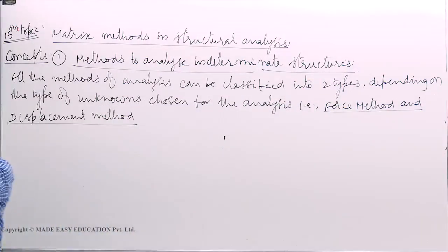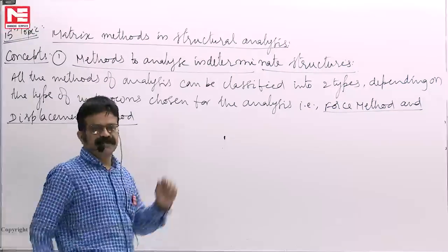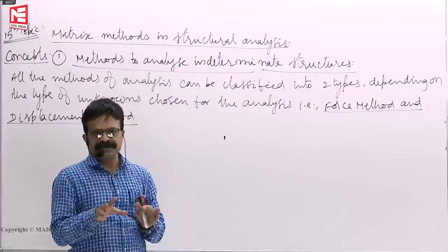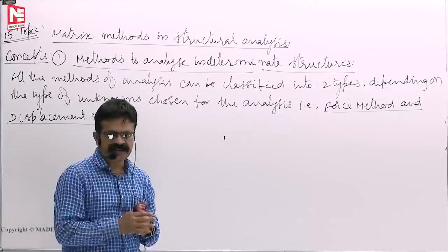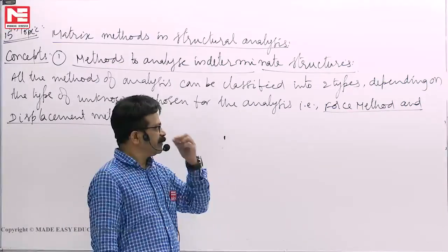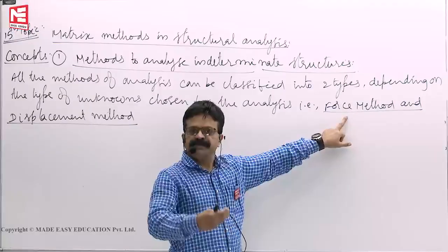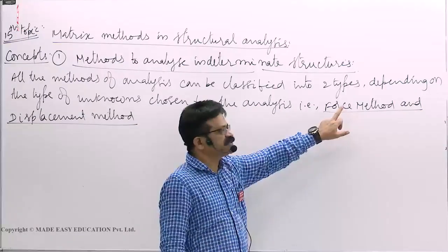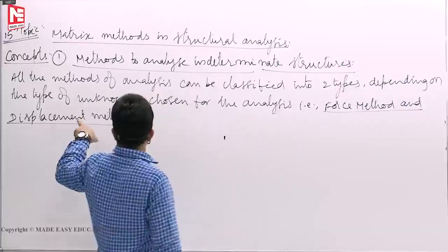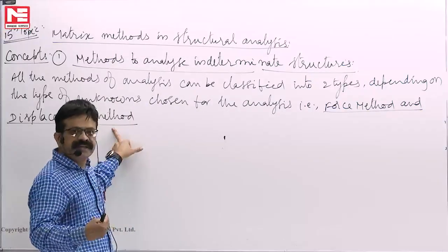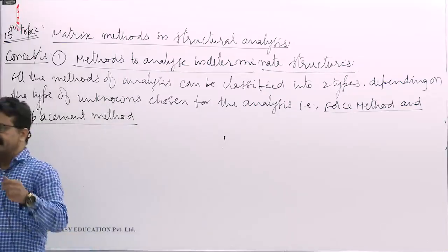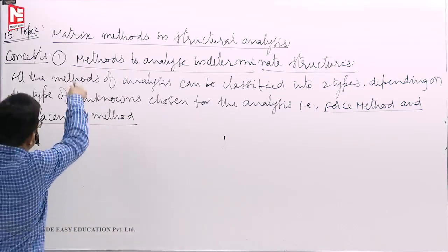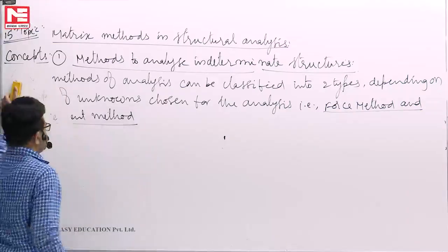Now, force method and displacement method, they are general terms valid for linear elastic structures, non-linear elastic structures you can apply. If at all force method is applied to linear elastic structures, I told you it is called flexibility method. Displacement method, if at all you apply to the linear elastic structures, it becomes a stiffness method. Like that. Okay. So we will list out the characteristics of the two methods.